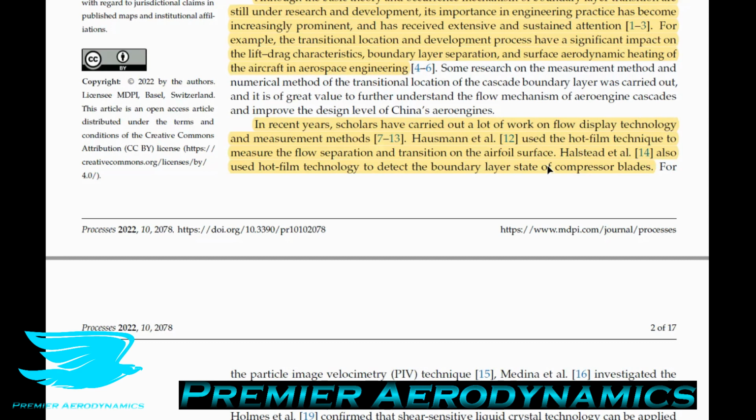One major difference, I should actually stress that the advantages and disadvantages of hot wires and hot films have sort of become blurred recently. Traditionally, hot films are significantly stronger than hot wires. They also traditionally had higher frequency responses. However, both of them have really high responses anyway, like tens of thousands of hertz are very common. You can get up to hundreds of thousands quite easily.